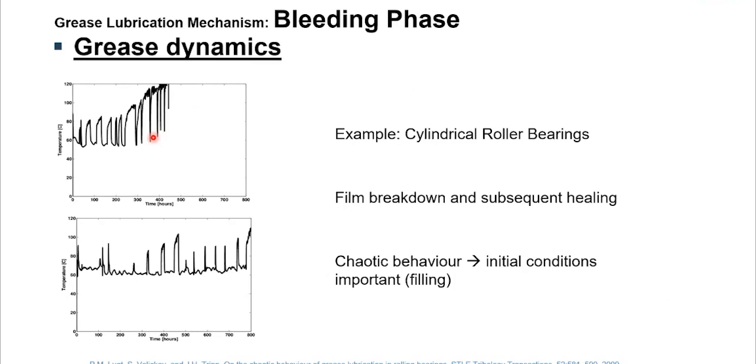So because of that, locally the temperature will rise. This rise in temperature will result in either more lubricant bleeding from the reservoir, or the possibility of the grease lump itself falling back into the contacts if it is loosely bound in the reservoir. So because of that, you have a micro churning for a short period of time.